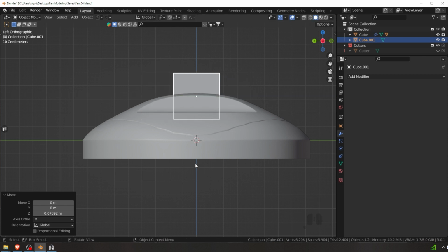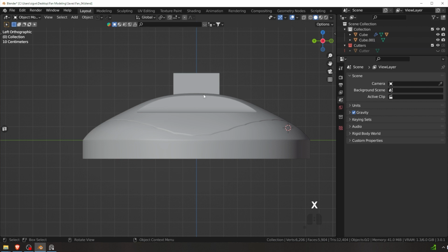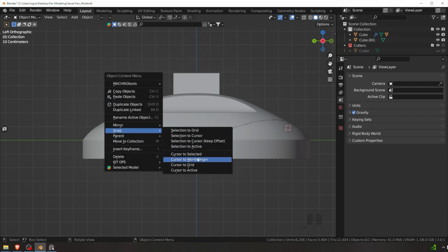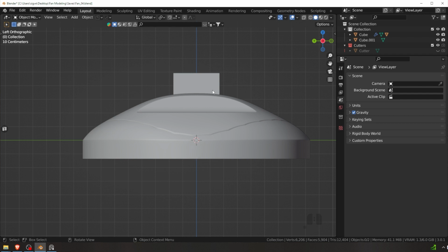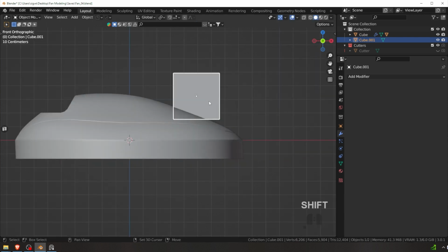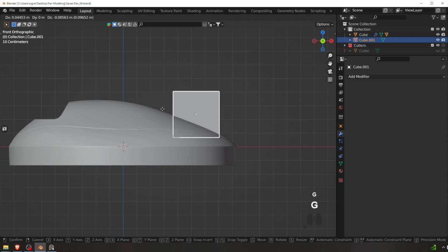If your object appears, let's say, somewhere else, you have this right here, just Shift A, and this will appear here. Then you can just simply right click anywhere, snap, and then cursor to world origin. And then this snaps right here, and you'll get new objects in here. And even if you scale, it scales from the center, so it's fine, it will remain in the center. All you need to worry about is z-axis and x-axis, so just change them in this view. Okay,